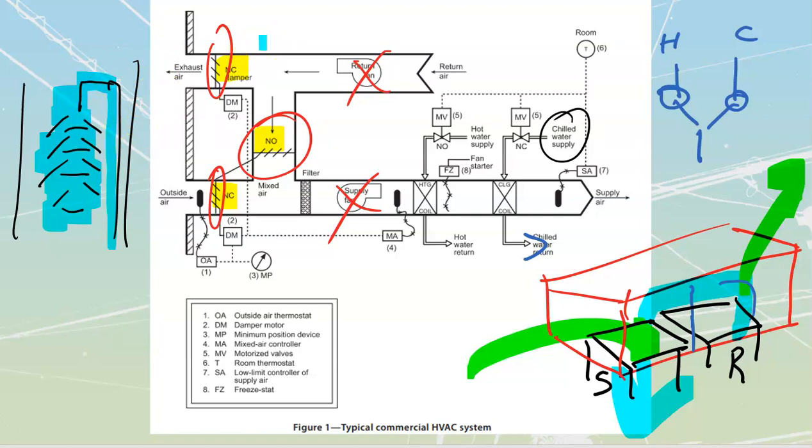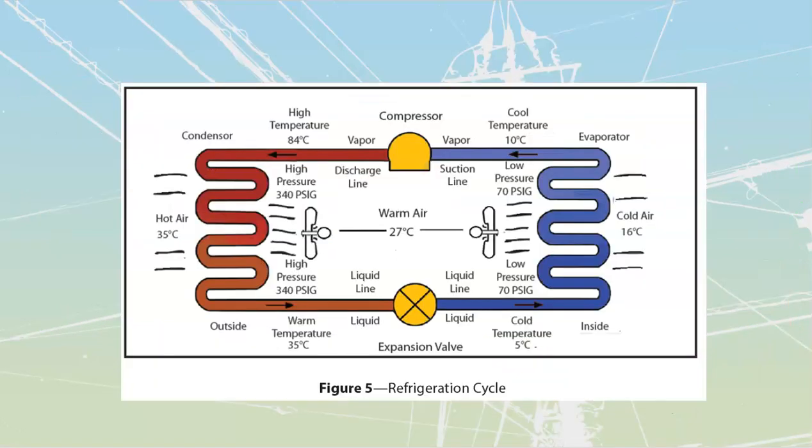It's your chiller tower. It is only going to remove high amounts of heat in relation to your outside atmosphere. If your outside atmosphere is 20 degrees, you would be able to release anything that is hotter than 20 degrees, but you'll never be able to take your temperature below 20 degrees using something like that. If we do want to actually heat and cool, what we need to use is something referred to as direct expansion.